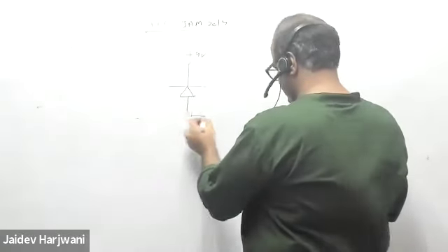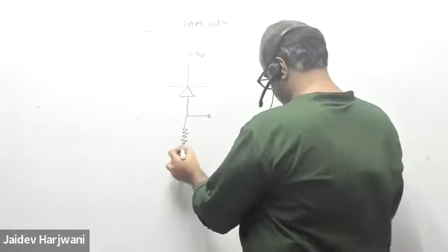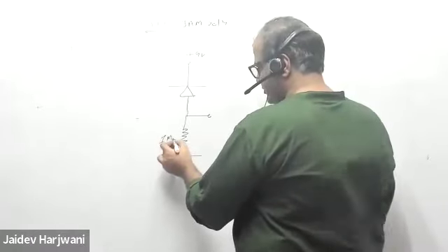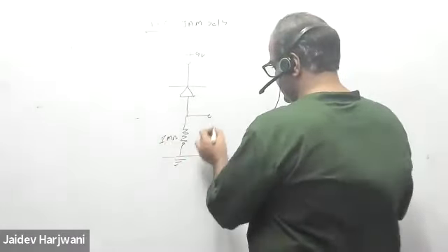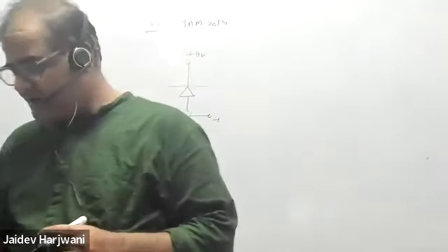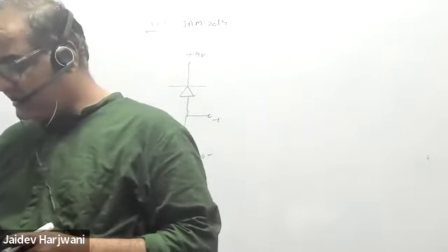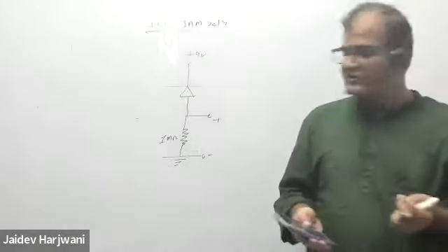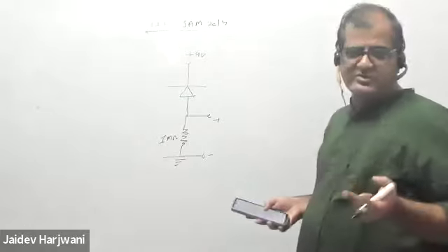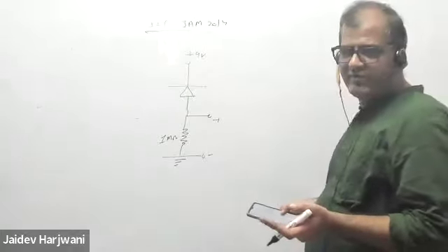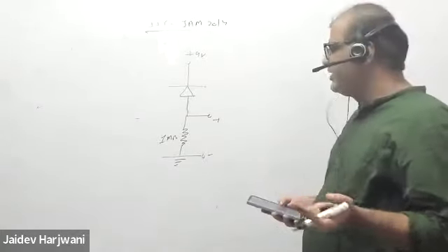So this is a 9 volt battery. Okay, and this is your 1 mega ohm resistor given. Okay, and this is the plus, this is the minus. Okay, so in the question he's given that the diode in the circuit of the figure is a large high current device whose reverse leakage current is reasonably independent of voltage. So leakage current flows in the resistor, of course, this diode is reverse biased, so some reverse saturation current will flow. Whenever a diode is reverse biased, leakage current will flow. Okay, reverse saturation current, that is independent of this voltage drop here.